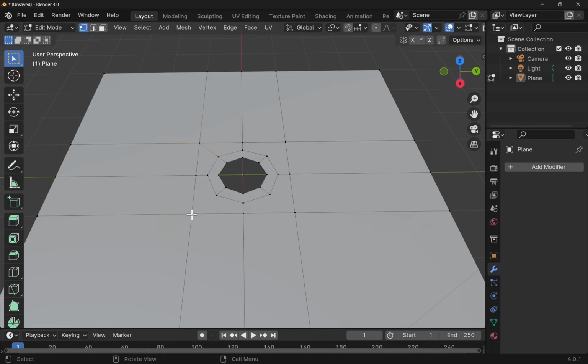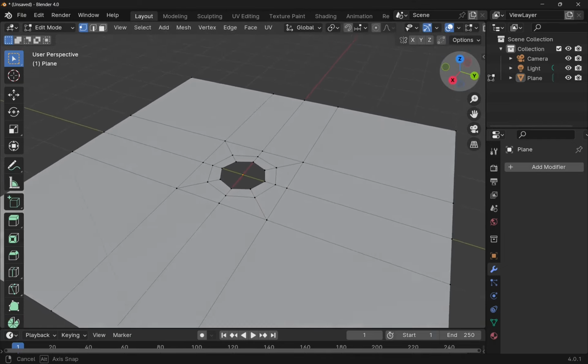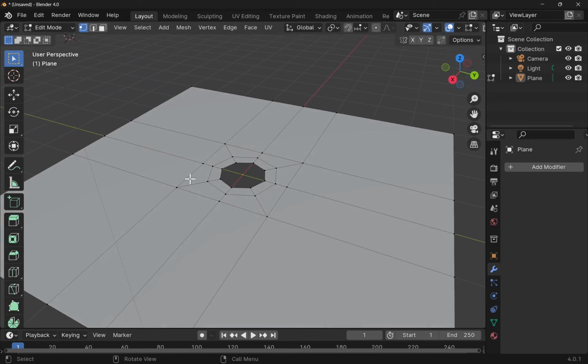Repeat the process, and this time I'm going to use a shortcut. Select one, shift select the other, and hit J on the keyboard. And work our way around doing the same. We're building up clean geometry. Also, the insides need doing, so I've got one here, click J, and this one here. And we'll do the final ones at the bottom and top. Once we're finished, we have something like this. You can see how that hole is supported by the geometry.